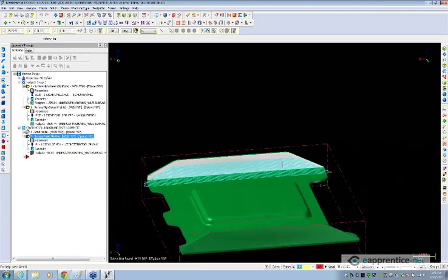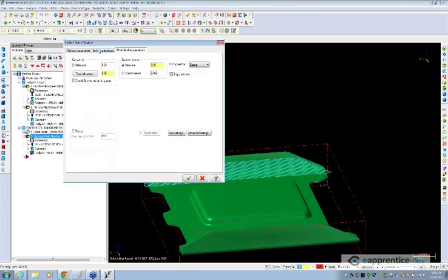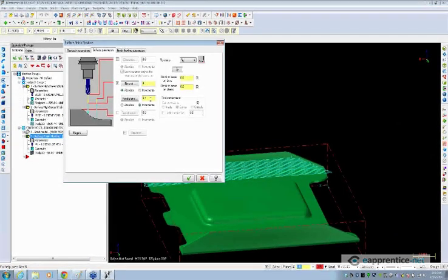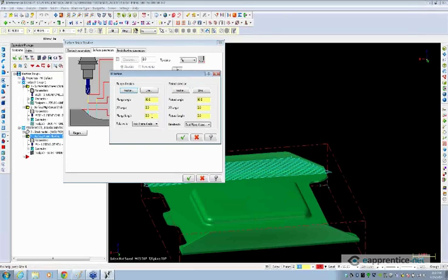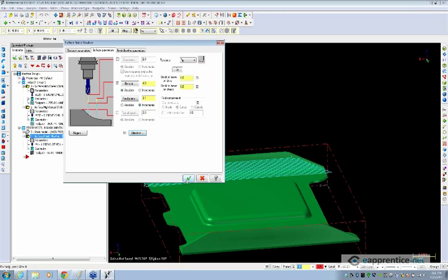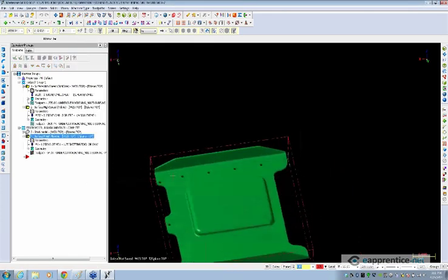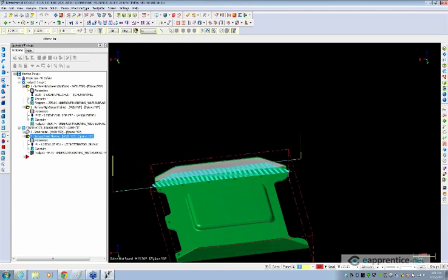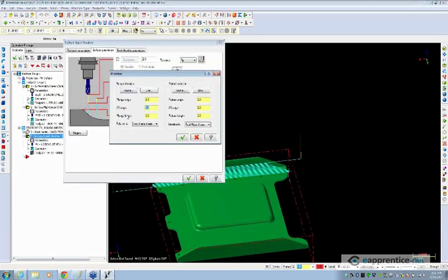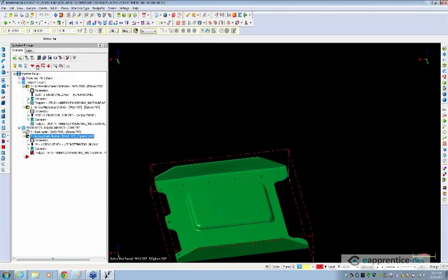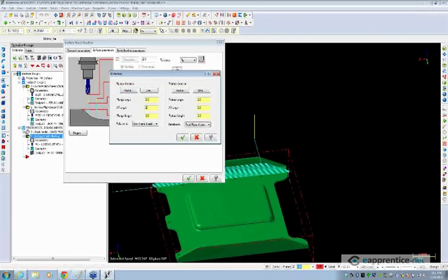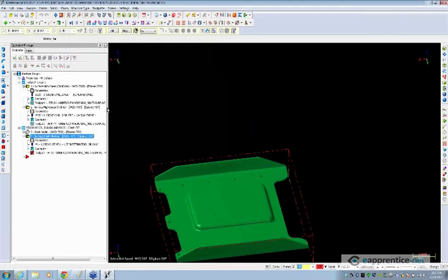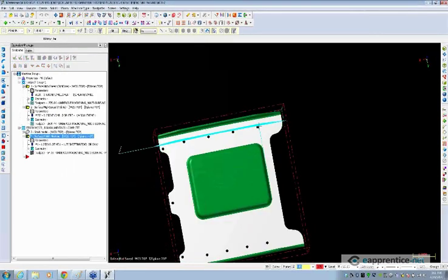Okay, so again, typically I would use direction for this. So we'll go back in here and set up direction. Let's do a plunge length of 3, and 0, 0, and XY 0, 0 relative to the tool plane. Again, I set them big just to see what I've got. All right, my entry motion is coming in this way. I'll adjust that one first. So we'll go 90. See if that's correct, or if we want, nope. Now it's plunging through my wall. Definitely don't want that. We'll go back and adjust that to 270, and that gives me a nice entry motion this way.